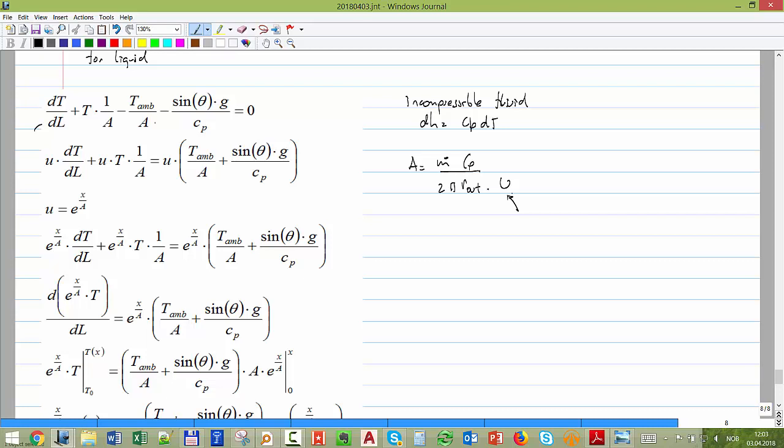Normally you have forced convection inside. That's what you're calculating in the wax exercise. You have T of the fluid all the way to T of the wall. That part is forced convection. Okay, this part is conduction.